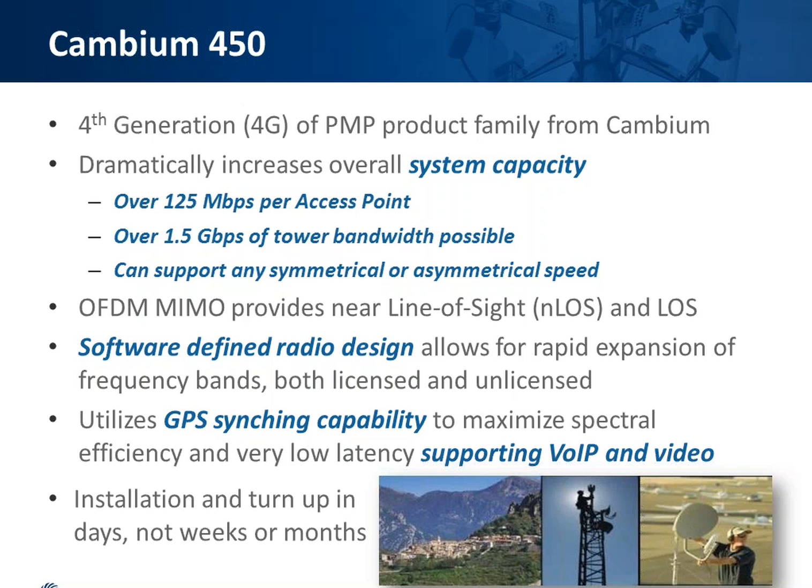And as we expand into more and more frequencies, we're able to do more and more things with this platform. It can support asymmetric or symmetric speeds, with uplink and downlink duty cycle. It provides near non-line of sight, as well as being optimized for line of sight connectivity. With the introduction of the 900 megahertz frequency band, we can now support non-line of sight in a very effective manner as well. It's software defined, so we're able to proliferate many frequencies and expand this platform and do lots and lots of things that we would otherwise be constrained from doing with an ASIC or a more constrained protocol.